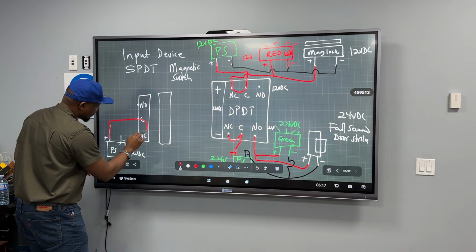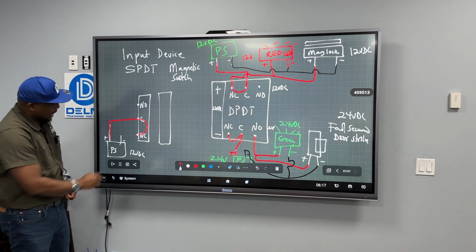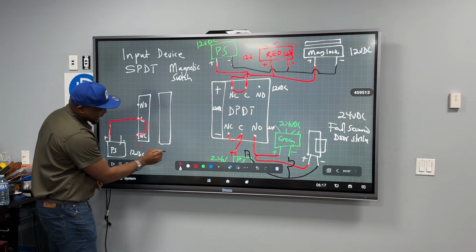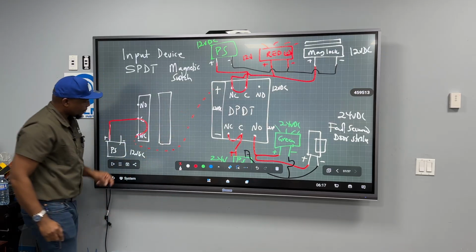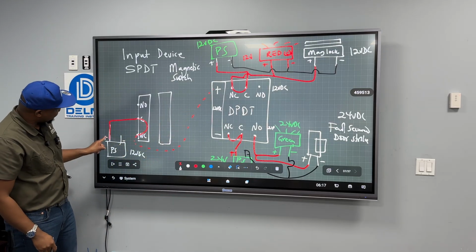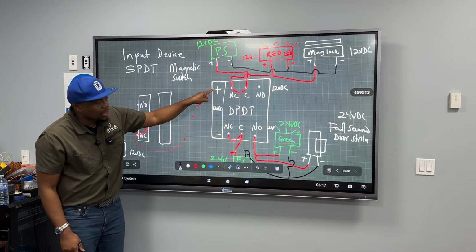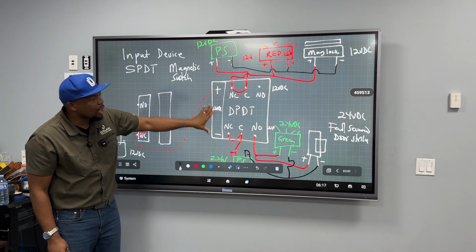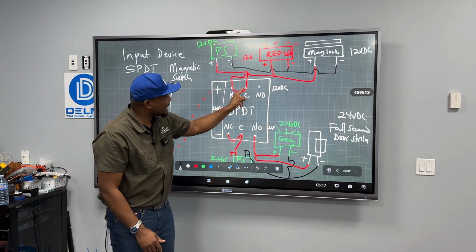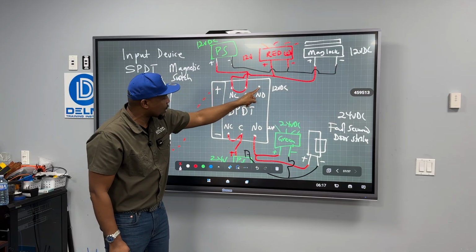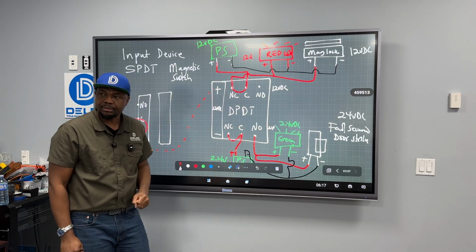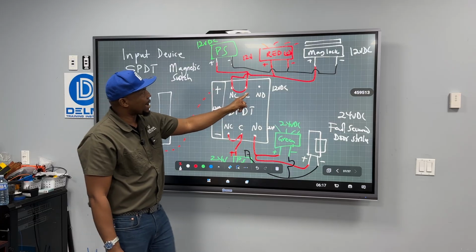Here. Yeah, this is normally closed. If I took this and I connected this here like this, this is the normally closed. Any voltage that I brought in here is going to show up here, and it's just going to come here. So this coil is always going to be energized, and this is going to be permanently locked on the normally closed. So what is going to happen?